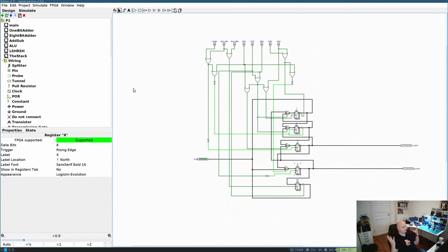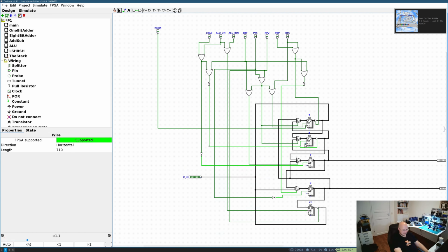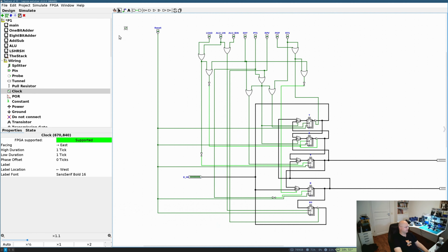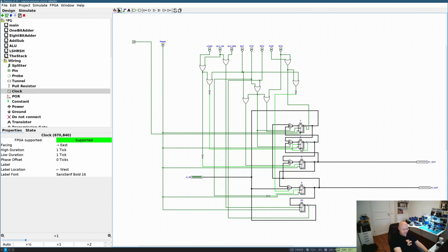In case I would have an FPGA or even in Logisim, you can set a reset value for each register, but in the physical hardware that I'm going to use, it always resets to a 0. Well, there are some versions that reset to a 1, but I'm going to use the one that resets to a 0. You cannot set a value, because otherwise you will need 8 more pins for the reset value input. And I will have another circuit that will generate a reset signal after the power up and reset all the registers to 0. And this is why I would like to have my NOP operations be all zeros, because that's the default state of the registers. Plus, I need a clocking input.